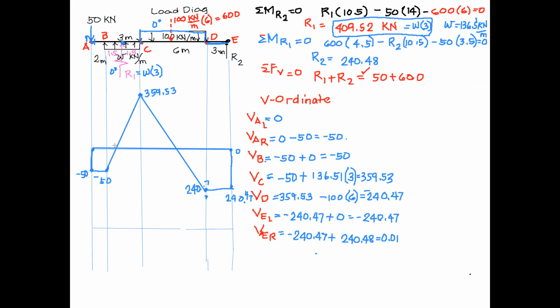So this time, our shear diagram crosses the reference line twice. That is where the points will have 0 shear. Whenever shear is 0, we expect maximum positive or negative moment. So those are supposed to be added points. We call this A, this B, this C, and then D, and then E. Those two are very important. We call this F, and we call this G. A, B, C, D, E, F, G.